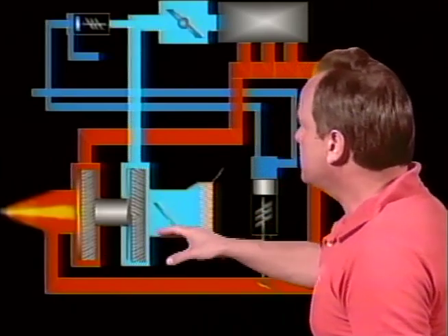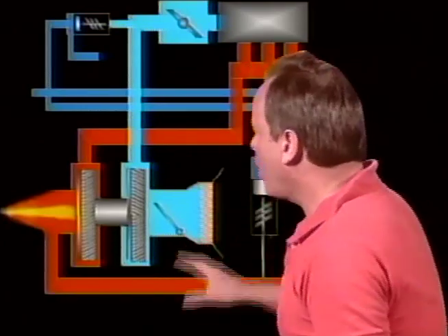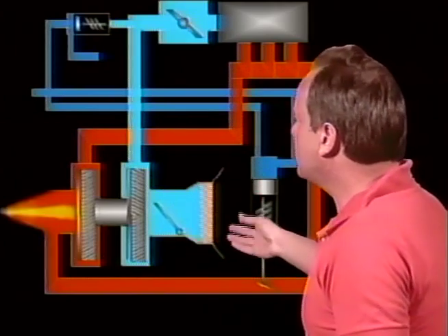If, on the other hand, all the turbocharger does is keep the manifold pressure somewhere around 30 inches or less as you climb up to higher altitudes, it's called a turbo normalized system. What a turbo normalized system does is make the engine think it's breathing sea level air even though it's at higher altitudes. Let's talk about the design of a sea level boosted system.